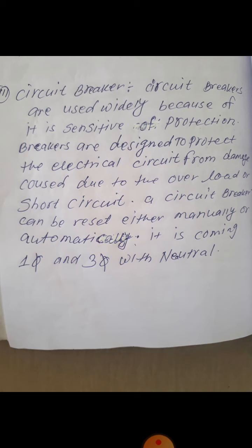These are the fuses, and these are several switches. You can see 4, 5, 6 switches in one gang switch box. On the side there is this type of gear, and this is also an old model. This is also used in our three-phase supply, coming directly into the cubicle fuse system, and then going to the DB or distribution board. This is also an old model, mostly not used now. Next one is the circuit breaker.